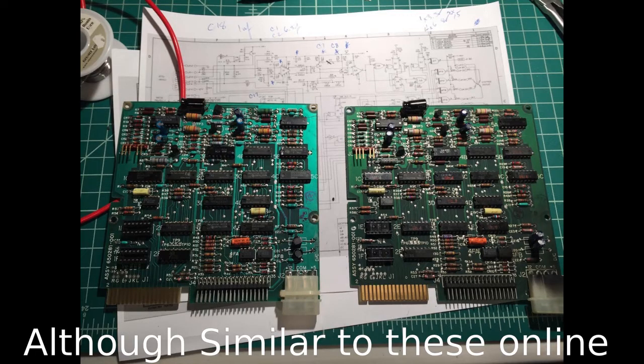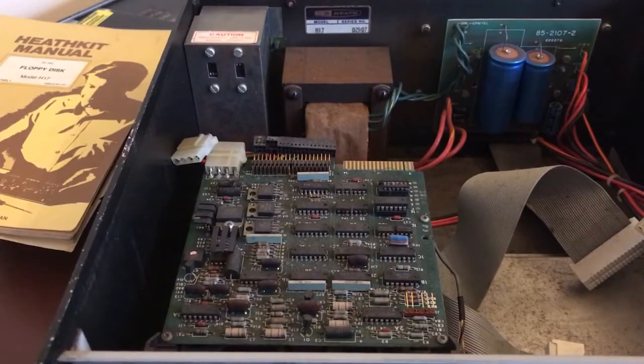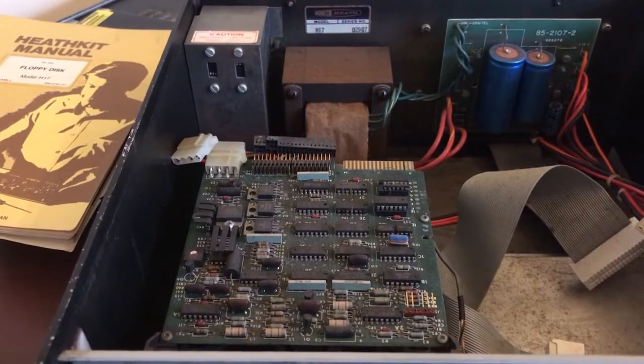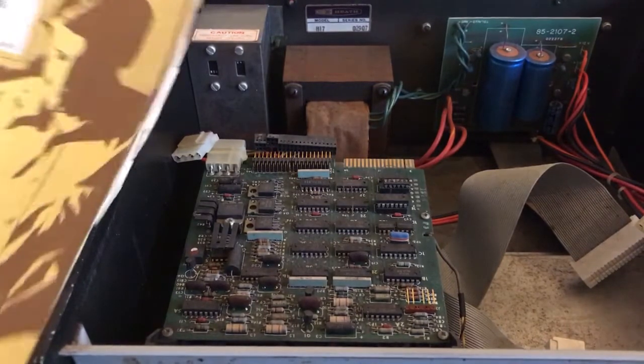There must be a drive speed control board somewhere as well on that drive, so I'll probably have to get it out and lubricate the drive, clean it all off. All the old lubricant will have gone seized. You just clean that off with some isopropyl and some very light machine oil, just dabbed into 1 or 2 places where there's contact. Should get the drive mechanism freed up and running. And then we'll try it with a sacrificial soft sector disc that I can afford to run, and we should be able to use the diagnostics from the manual.